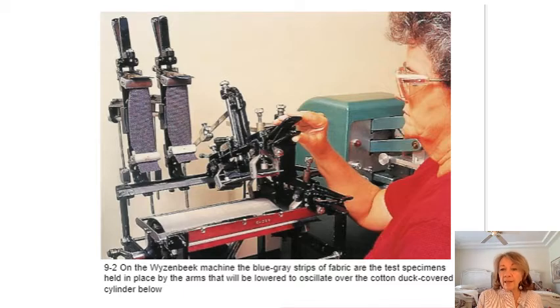And there are obviously inconsistencies in the test. You could have machine operator error. It could depend on how tightly the fabric is put into the machine, or how often the abrasive material is changed in the machine. But the manufacturers are looking for certain test results to see actually how durable a fabric is going to be. And fabrics actually fail the test when thread breakage occurs, or a fabric starts to look worn. So those are the things that they're testing for abrasion on your fabrics.